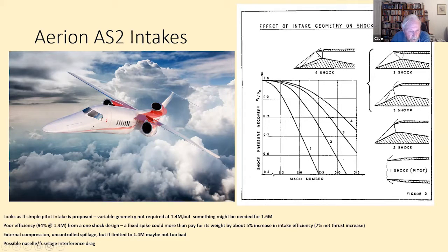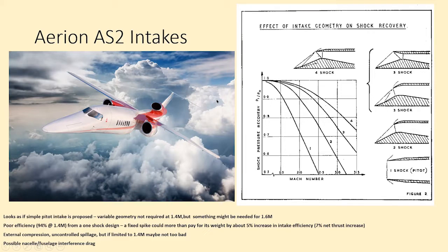I'm wondering about the possible nacelle to fuselage interference drag. There have been cases where nacelles quite close to fuselages, particularly where there's any fuselage taper, can give rise to drag. I'm sure they'll have covered it, but it's something that if I were asking questions, I would ask.